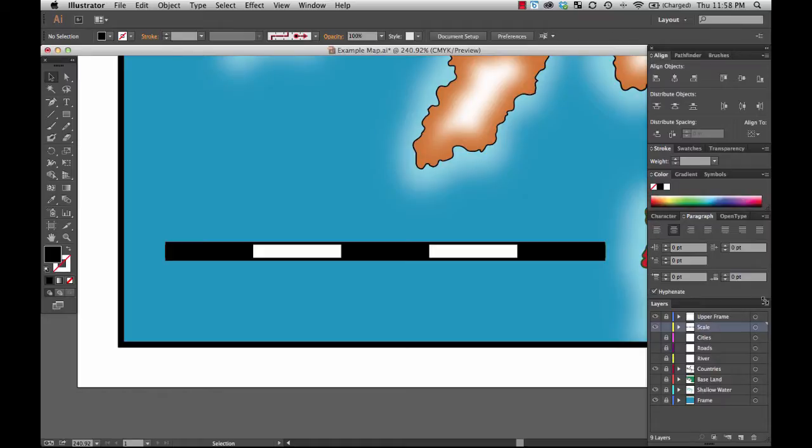So if you've taken other classes with me, or if you will go forward and start talking about the theory of cartography, then you will know that most of the time I like to see divisions before the 0, smaller divisions before the 0. Perhaps if you're doing thematic maps, you can get away with having just one scale bar that tells you a length because they're just for general reference anyway. But anytime that you're doing any type of map that's deliberately supposed to be read or studied, and one that especially is supposed to actually be used with a ruler in order to get a distance off of, you should put divisions before 0. In some particular case, I'm going to show how to use a scale bar to determine distance on a map. But if you do use maps and you do use a scale bar to get distances off of, you know that it's very, very handy to have a smaller increment before the 0.